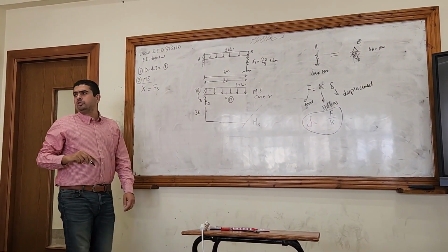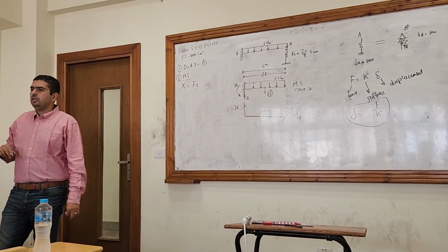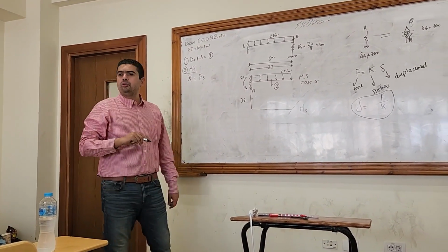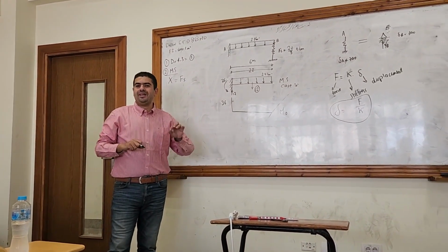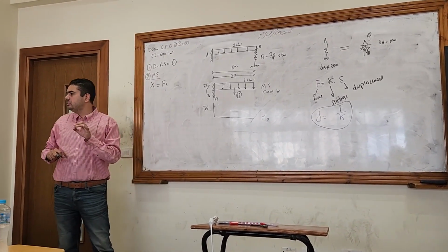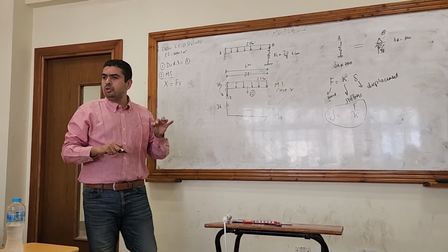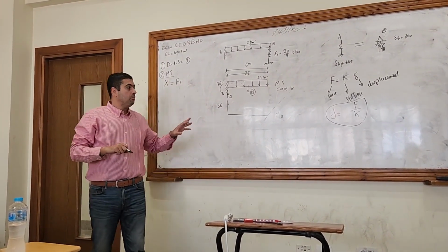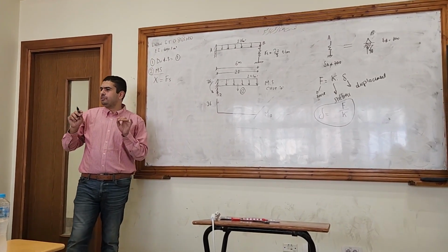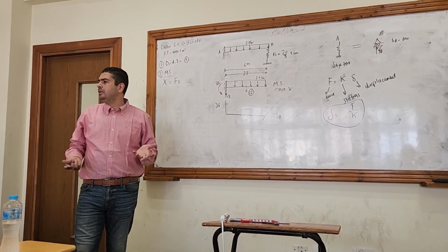Do you remember how can I draw the bending moment for a uniform distributed load? In Structure 1, we used to draw the curve exactly. So we used to use 3 tangents to draw the curve, right? But here in Structure 2, we don't need this accuracy. We are just drawing without scale.